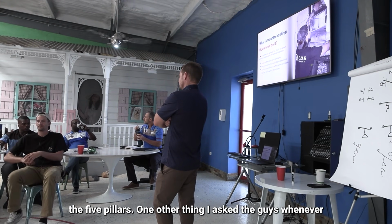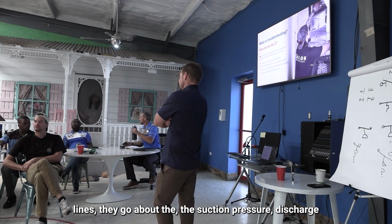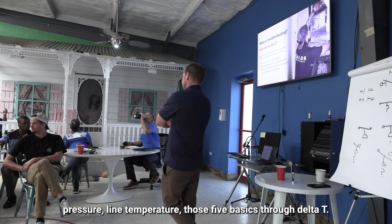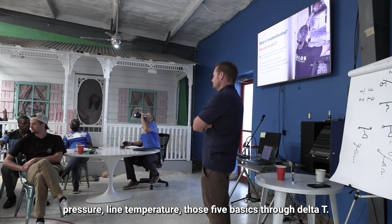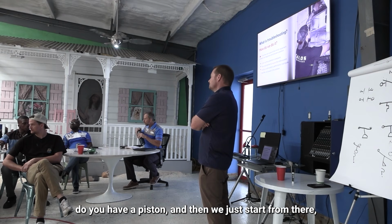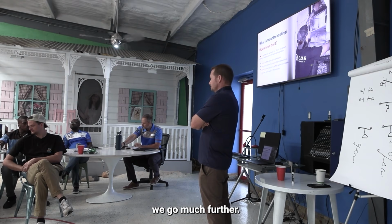One other thing I ask the guys whenever they call me over the phone for something along those lines: they go through the suction pressure, discharge pressure, line temperature, those 5 basics, to your delta T. Also, just add to that, do you have an expansion valve? Do you have a piston? And then we just start from there and move on. But I try to get that much information before we go much further.